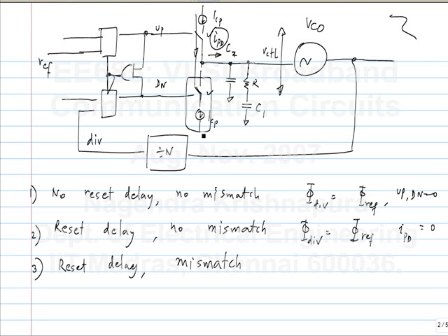It can be at the top, it can be at the bottom, that depends on the implementation. But whatever it is, over this entire voltage range, the current source should behave like a current source. A real current source always has a voltage limitation, right? If you use an NMOS transistor as a current source, it won't work if the output voltage is very small. Okay? So, you should design it so that you don't constrain the range.